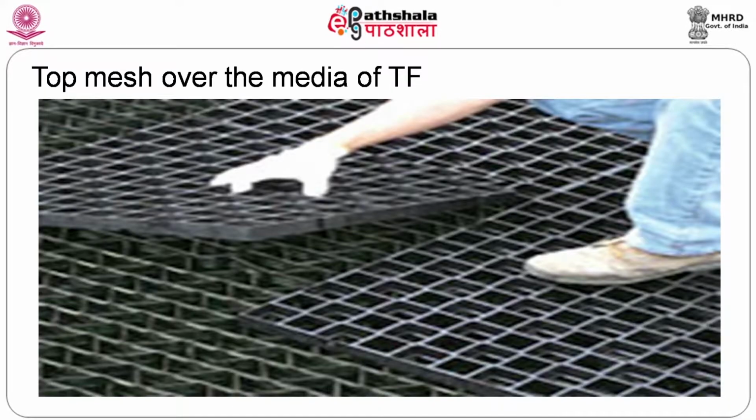The growth is a continuous phase if you operate your reactor in a continuous manner. So, in order to control the growth, we have to consider organic loading rate as well as hydraulic loading rate at an appropriate level for continuous sloughing of the media. By this way we can maintain active microbial film thickness for better transport phenomena as well as better BOD removal.